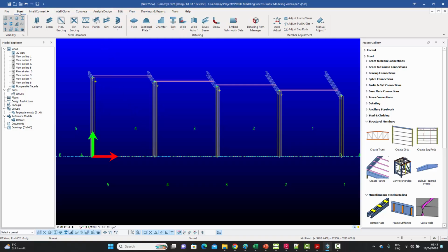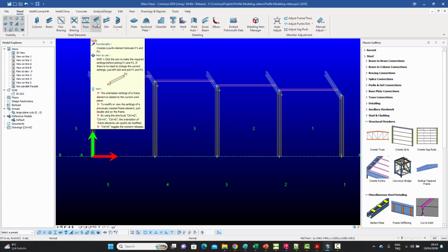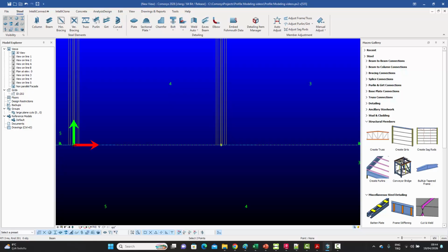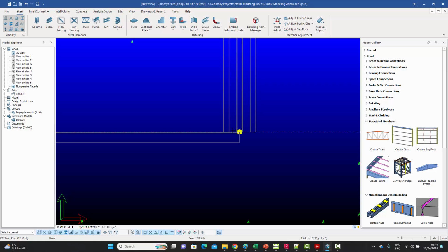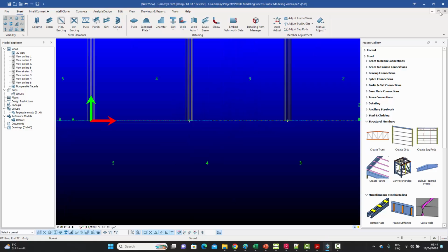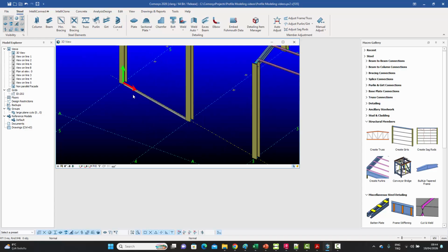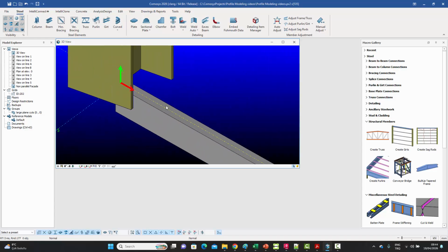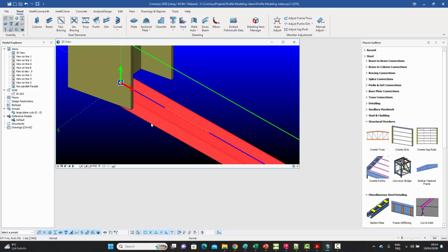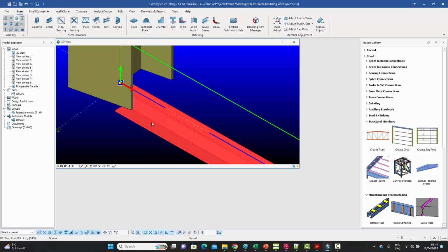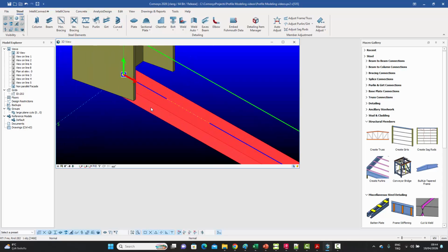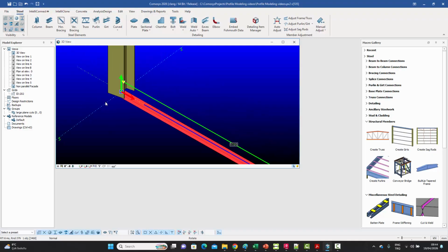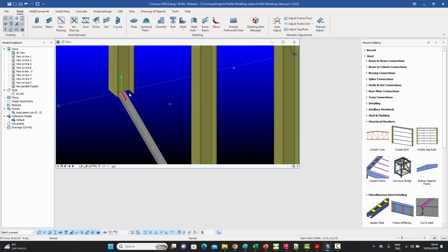So you go to your steel menu and you click on the girts, for example, and let's just create it at the base first. We'll move it 300 millimeters like that. And then we can go back to the 3D view and see how we've placed it. So this is the way it's placed it. Let's click on it and press Control Q a couple of more times, so it's looking down. Now maybe I can just select the origin of interest somewhere over here and see it a bit like that.